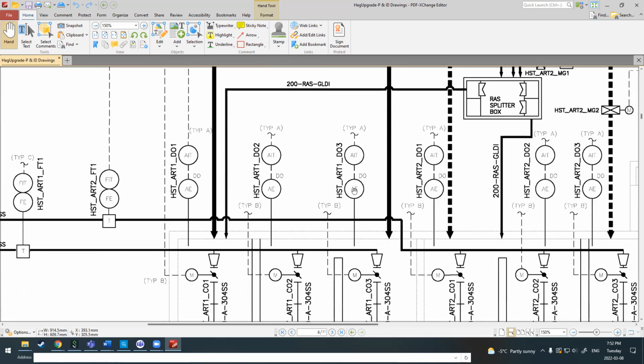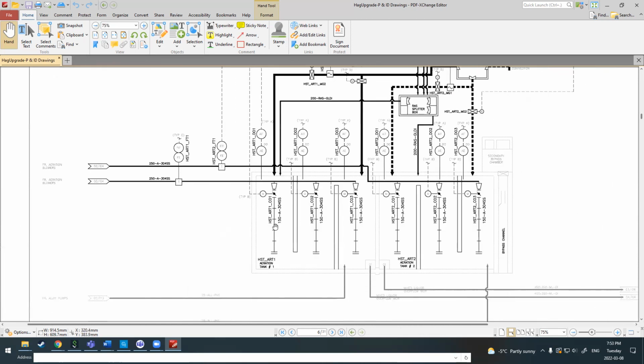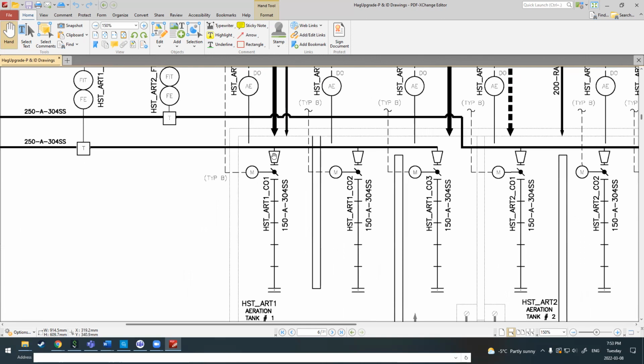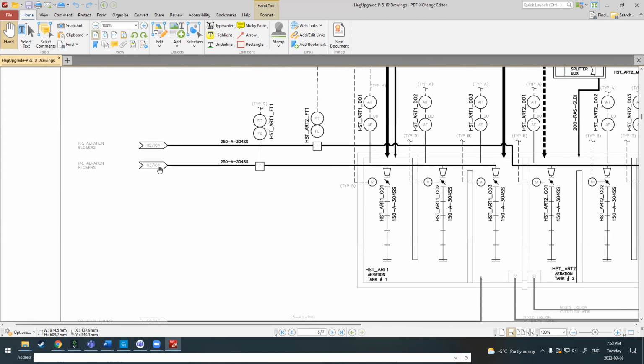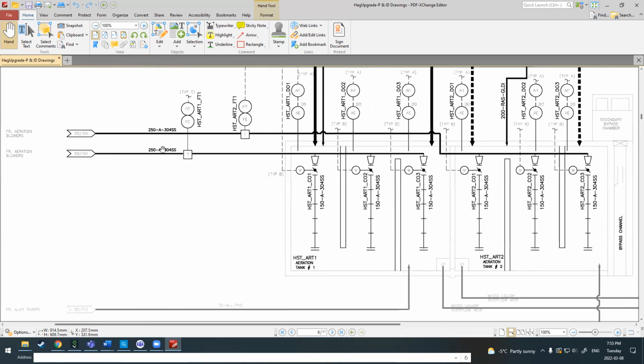Here we have a aeration dissolved oxygen sensor. So it's actually measuring the dissolved oxygen inside the tanks. These are giant. So here is a giant air diffuser, actually. So this is processed air. Here we have air from the aeration blowers. Again, these lines could be any media, and wastewater is a really good example of multiple medias. So there's air being blown down these pipes. The air comes down. Here's a mass air flow meter.